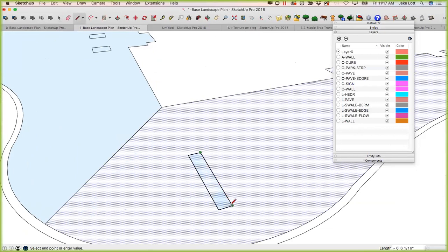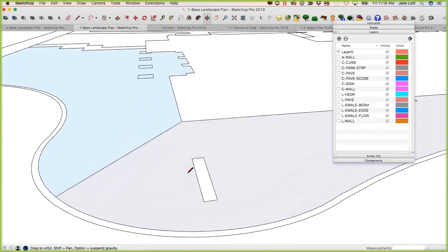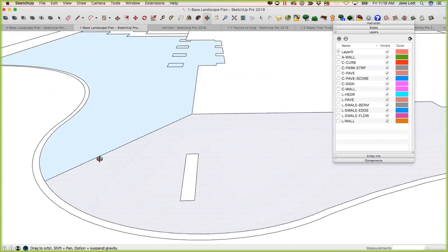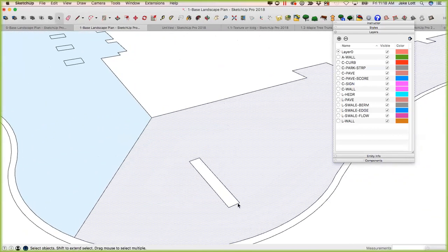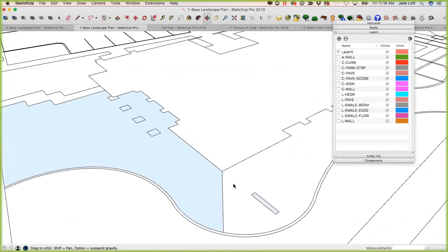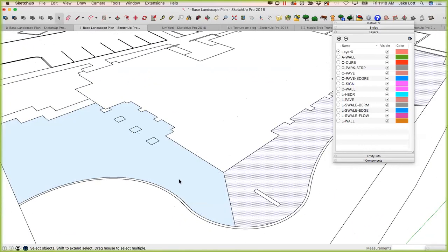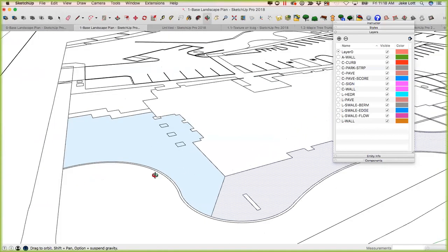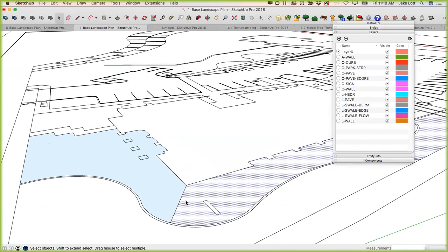because if you see that double kind of scratchy looking there, that means there's a face on top of a face. And you can tell that this dark line means that it didn't actually cut into this. So this is a solid surface here, but I've got a piece here. So even if I were to try to draw over this line, it was recognized again now, and it's cut in. The thickness went away, and now I know it's good. But you notice the difference in the color.